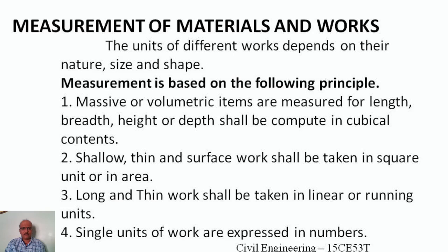of measurement depend on the massive or volumetric nature of the work or the item. For massive works like concrete foundation, random rubble masonry, brick masonry, etc., the measurements of length, breadth, and height or depth shall be taken to compute the volume or cubical content. Hence, these volumetric or massive items are measured in cubic meter.